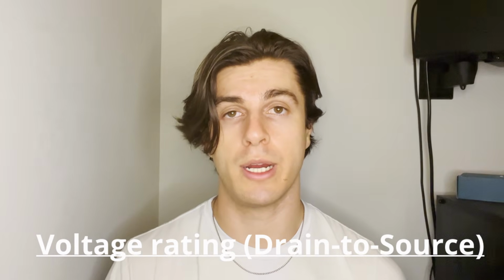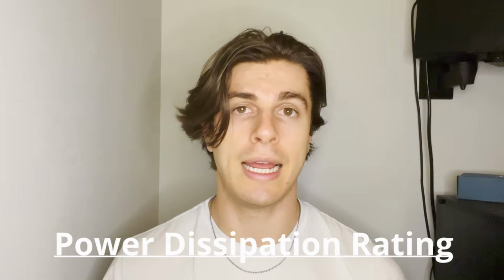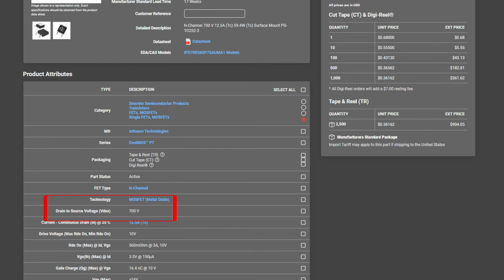The key parameters you need to be familiar with when selecting a MOSFET for your flyback converter application are going to be things like your drain to source voltage rating, your current rating, your power dissipation rating, and the thermal characteristics of the MOSFET. Note that just like with our input capacitor, you'll usually see some pretty high voltage ratings on your MOSFET because their input voltage is so high. So it's not uncommon to see MOSFETs rated at 600, 650 volts. And we'll talk more about why that is the case later.